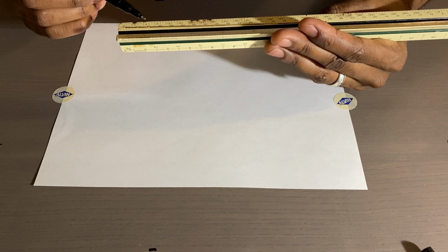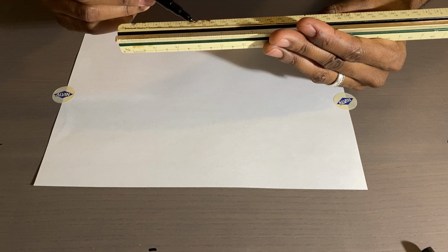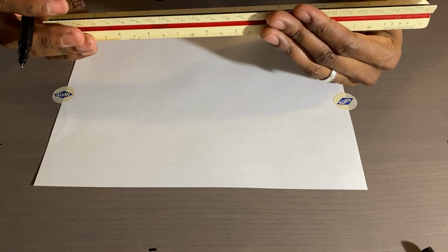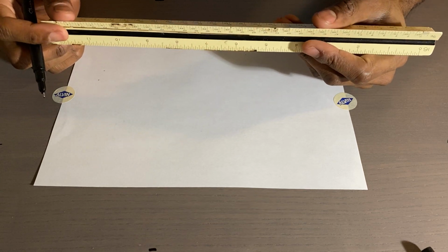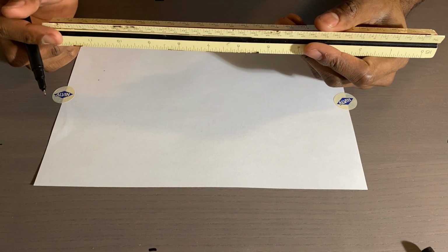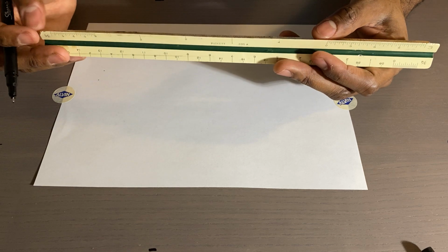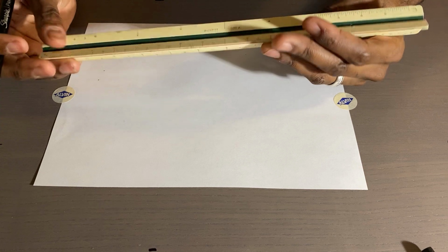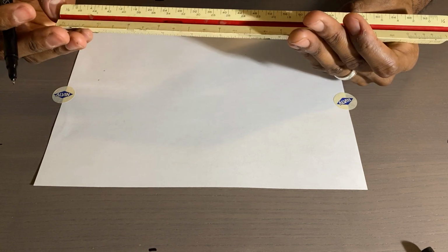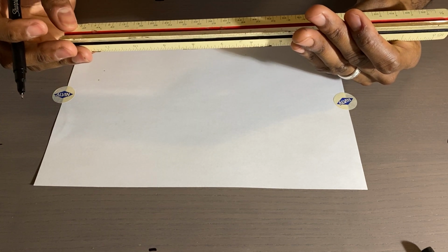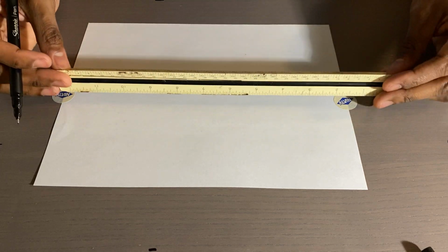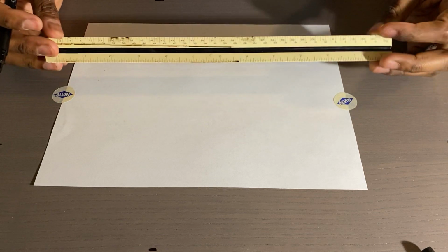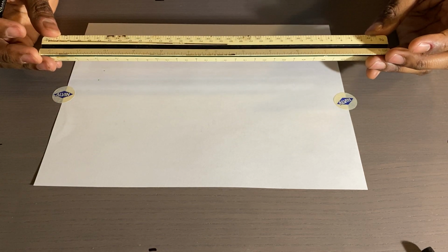So each of these are 3/32 of an increment, and each of those increments equals 1 foot. It's a smaller scale. Okay? So you want to find the scale that, A, fits on the paper, and then B, allows you to sort of draw the ideas that you're trying to draw. And so I think going with an 1/8 inch scale is going to be slightly too big. So that means I'm going to go to a smaller scale, and probably the 1/16 is going to be better. Yeah.